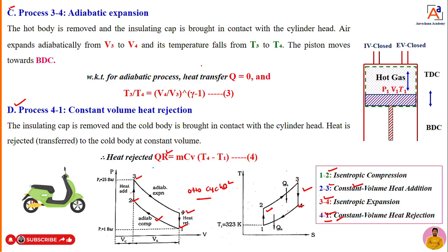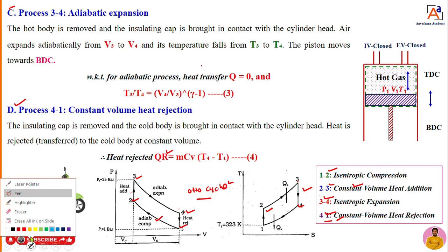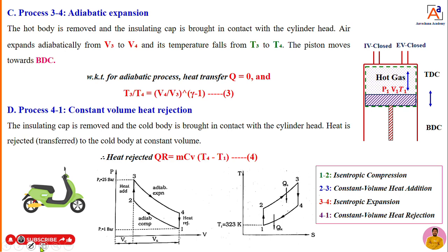Okay, dear students, that is very important here. During the Otto cycle, we supplied heat at constant volume and rejected heat at constant volume. That also needs to be considered. The heat is added from 2 to 3. What is the volume now? On the horizontal axis is volume, and pressure is on the vertical axis. Now you draw a vertical line, then points 2 and 3 lie at the same point on the volume axis. That means V2 is equal to V3, a constant volume process.